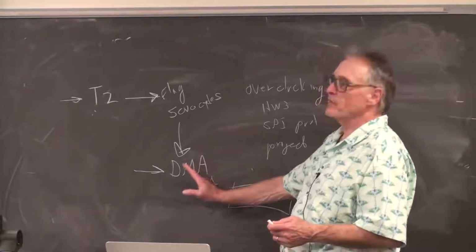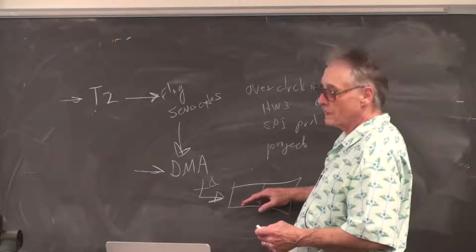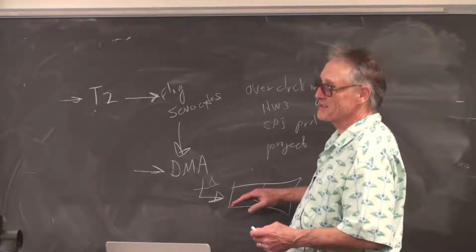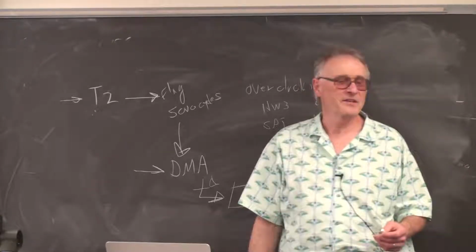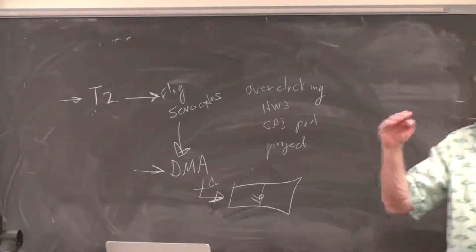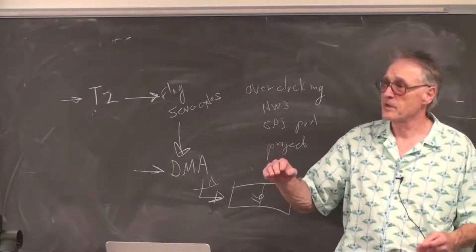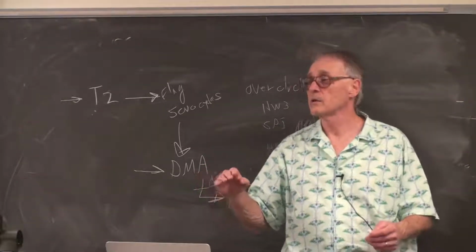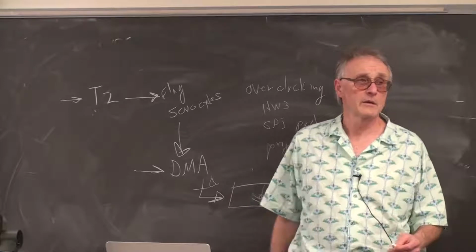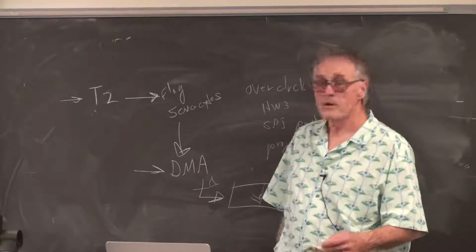Setting up the DMA for a 2-byte transfer, sending it to a framed SPI, in fact works, because I tested this. And so I don't know what the interlock mechanism is. That is even below the level of the hardware reference manual in terms of abstraction. So I don't know the answer to that. Good question, though.